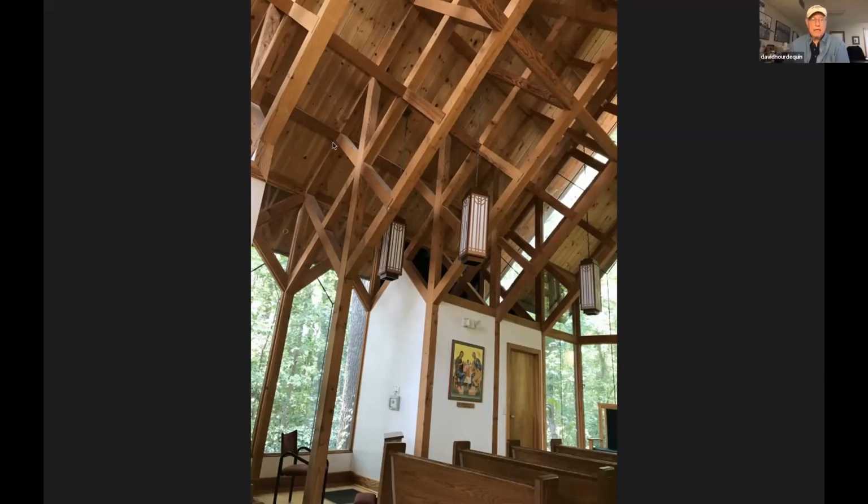Thank you, Josh. And just a terminology note for those of you that are not into heavy timber engineering or timber framing: this post and the adjoining truss right here all the way across the other side is typically what we call a bent in timber framing. And so what Josh was talking about pre-assembling is this entire frame laying flat down and then picked up with a crane and set in place. And then you set the next one, and then you set the interconnecting timbers.